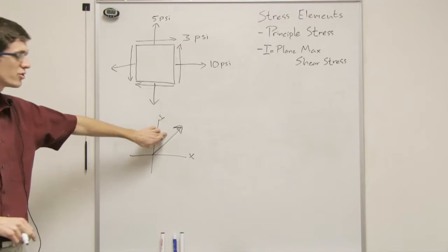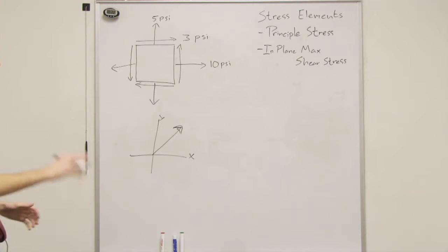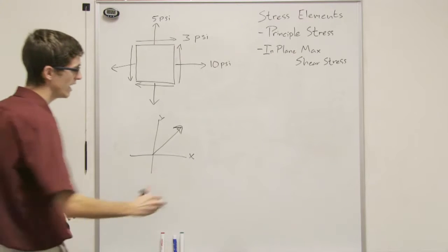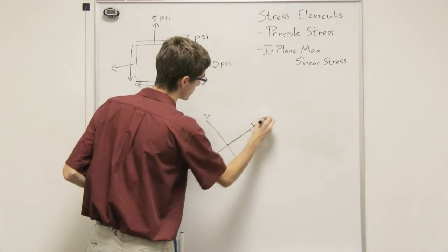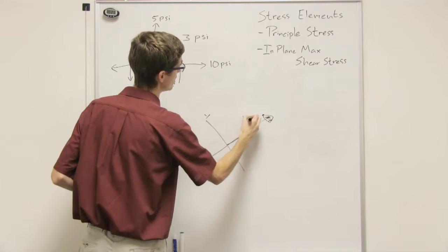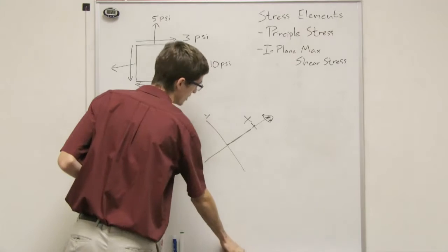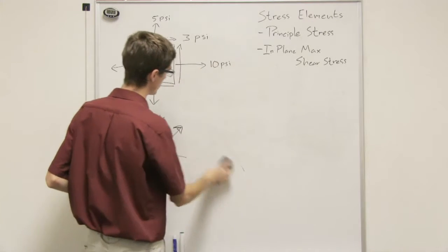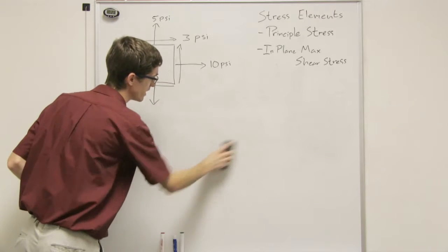If we wanted to get this resultant force right along one of the x or y axes, we'd rotate the axes so that we'd have an axis that looks like that, and then the force is running right along your x axis. That way your component force shows you what your maximums are. We're going to do that same thing with this stress element, rotating it so that we can find out what our maximum stresses actually are.